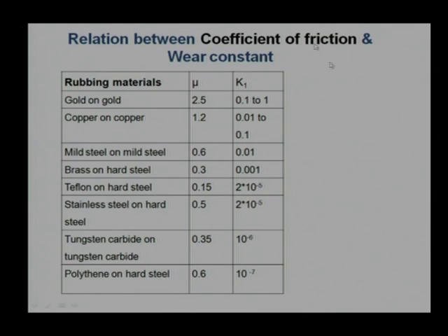Now, further from 1.2 to 0.6, you reduce the wear rate by 50%, and we are able to reduce the wear rate to some extent, but as this is given in a range, we cannot say exactly what the range is. It may be from 1 to 10 times. Reduce the coefficient of friction further from 0.6 to 0.3. Here we find a big jump, the wear rate is reduced significantly, again 10 times, from 0.01 to 0.001.